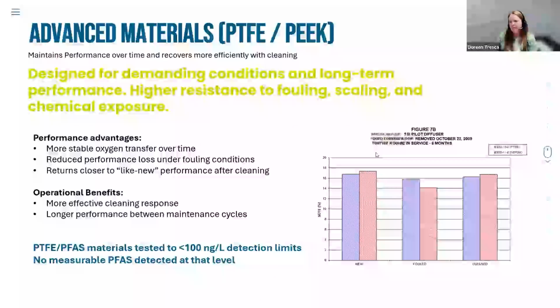Compared to EPDM, these materials are much more resistant to fouling and scaling, which helps maintain a more consistent airflow over time. One of the key differences is also how these membranes behave with cleaning. So you can see in the chart I have here on the screen, we had done some pilot studies. We had the diffusers installed for about 6 months in an industrial application, and we tested their OTE performance, both new, cleaned, and fouled. And you can see the differences between the EPDM and the PTFE membranes.